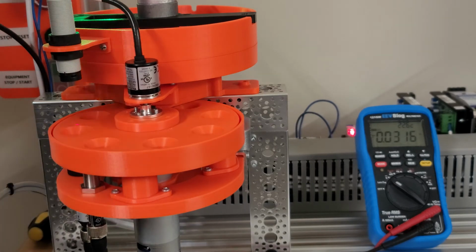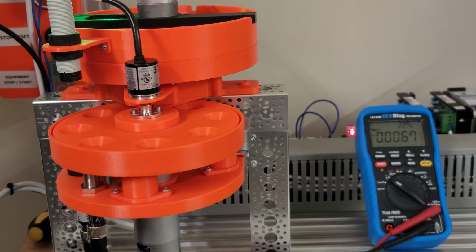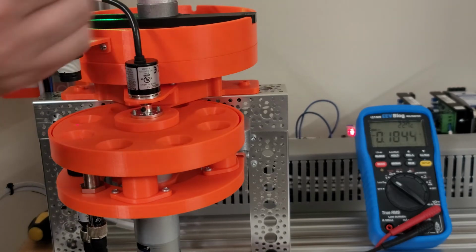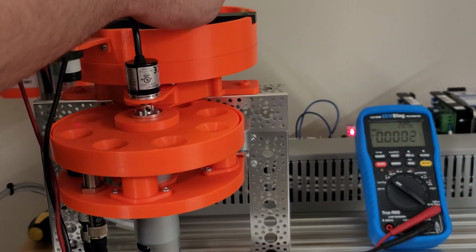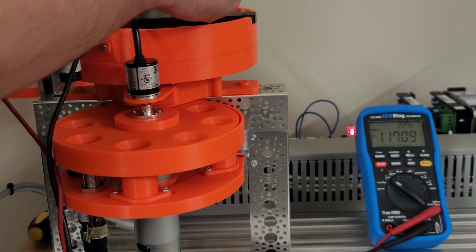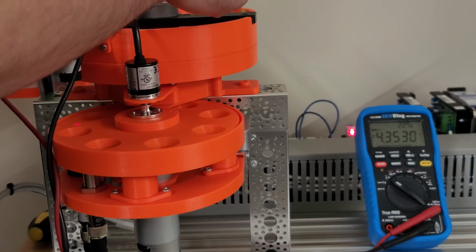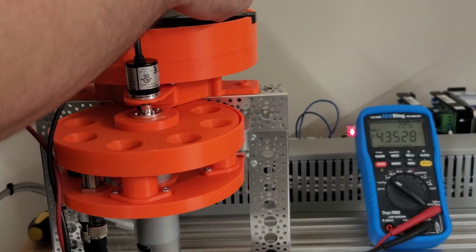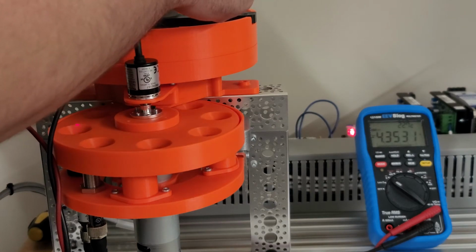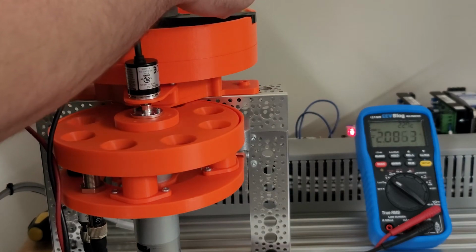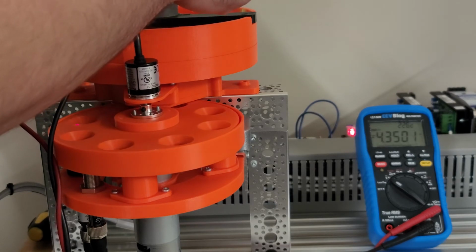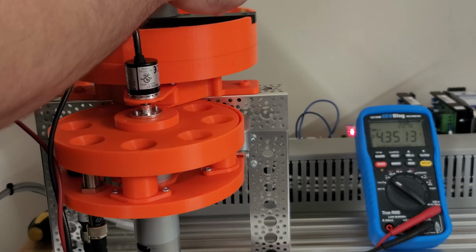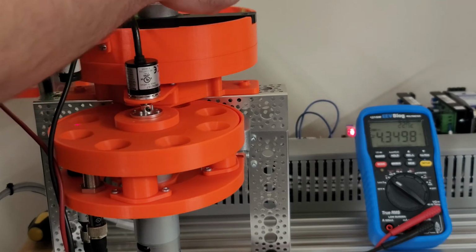The next thing we want to check is the voltage level going into each of the two motors. It should be half of the 12 volts, so that should be 6 volts going to both motors. So let's check that relative to what we saw. So to kind of sneak in here, we can see that the indexer is getting 4.3 volts, if I can keep the probe stuck on there. 4.35 volts or thereabout from the analog output of the drive.